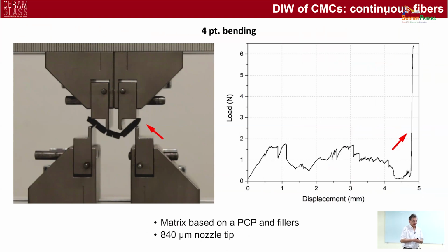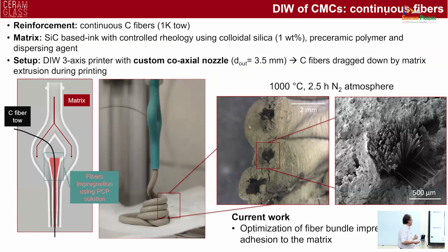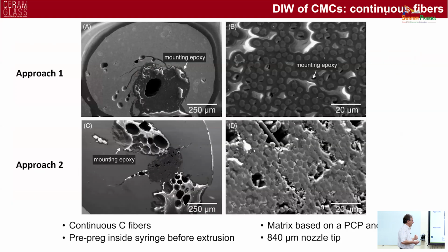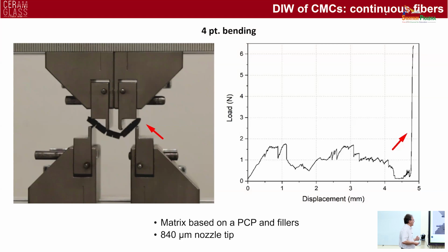But people correctly say that, I mean, these are data on mechanical strength, but they are computed based on the supposition that the fibers are placed in the center of the filament. And as you can see here, that's not always the case. So people that work with composites, they don't like this sort of test because it doesn't provide reliable mechanical data.